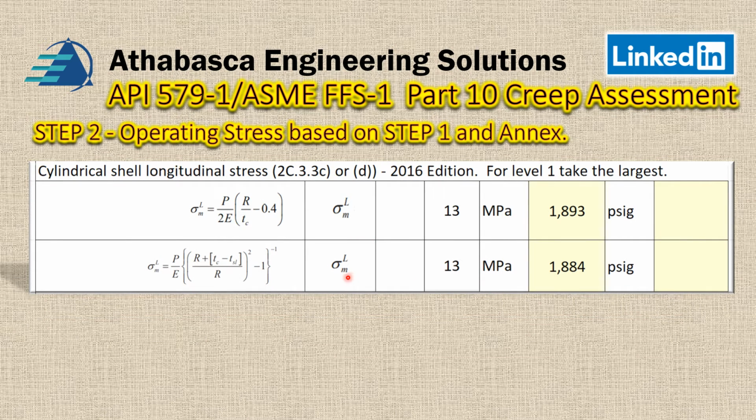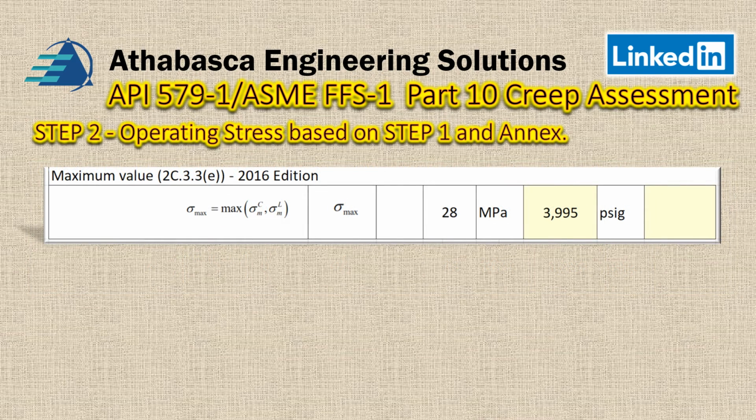The next one is to look at the longitudinal stress. On the previous slide we looked at the circumferential stress, and we use the same equations again, the corresponding ones. And of course, just as we expect, the stresses are half for longitudinal stresses, and that's how we do it. We summarize it, taking the maximum values. So we take the circumferential maximum and the longitudinal, and we come up with this value.